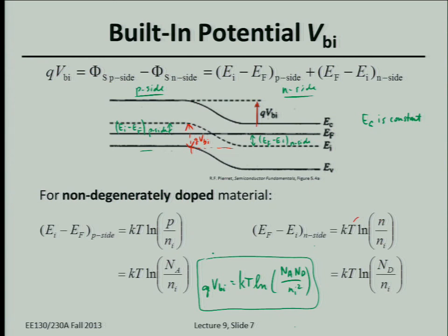That's a very complicated but correct answer. I like to think of it as you have more concentration gradient, right? You have heavier p-type doping on one side than the other, so you end up with a higher concentration gradient. When you make the p-n junction, the carriers diffuse across. But then an electric field builds up that creates a drift current that counteracts that. Drift and diffusion balance out in equilibrium.